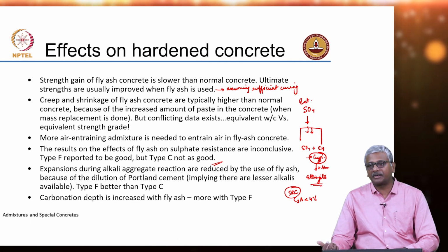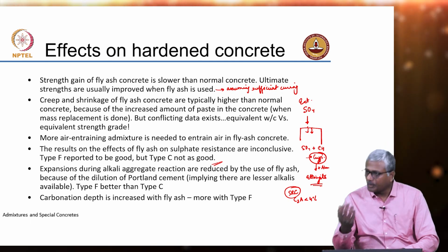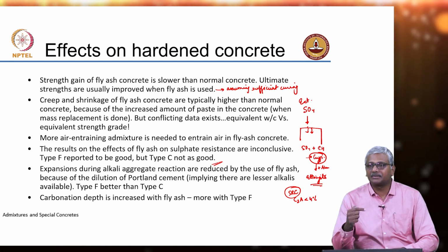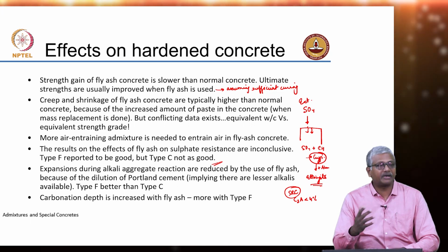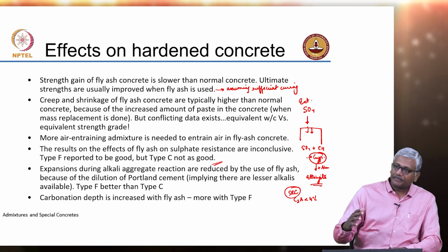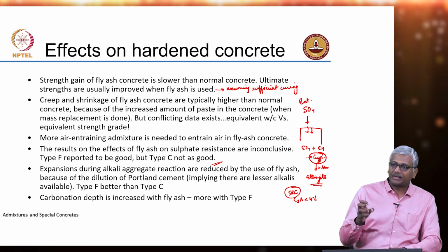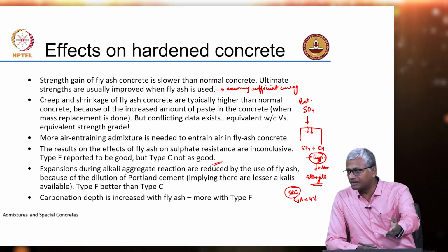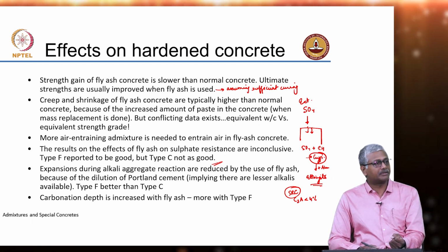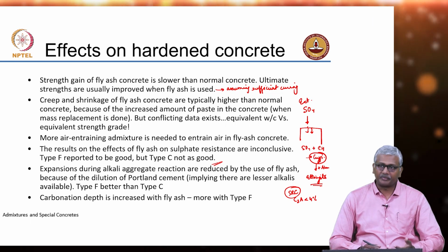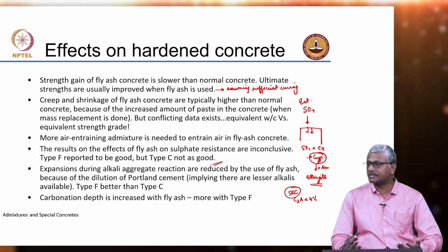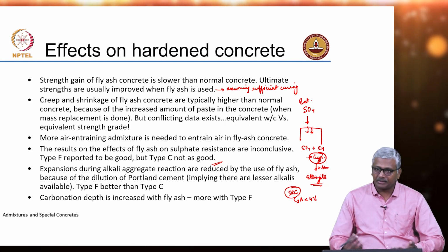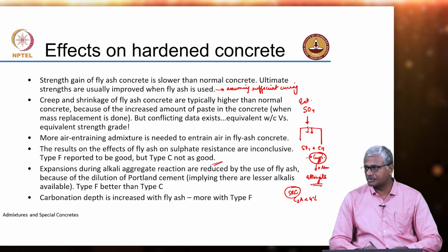Here with pozzolanic materials, the alkali binding takes place very soon because of the extremely fine particle sizes. In aggregate, this alkali binding and the subsequent reaction takes place over many years, and when moisture is available, that leads to expansion and cracking. Now, if these alkalis are not available to react with the aggregate and get bound by the mineral additive, then you already led to an improvement in the performance. So, the best way to protect against ASR is to substitute cement with any mineral additive. You will definitely see a reduction in the expansion that is happening because of ASR.